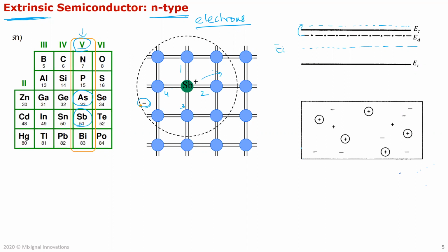And if you look at the block of the material, you can see a lot of these mobile electrons, right? And you also have these positive charges, which are holes. That's because even in this, some of the semiconductor might break like before, because they have enough thermal energy to break and create an electron, but that leaves a hole behind. So those are what's called generation. So a hole and electron pair is created.